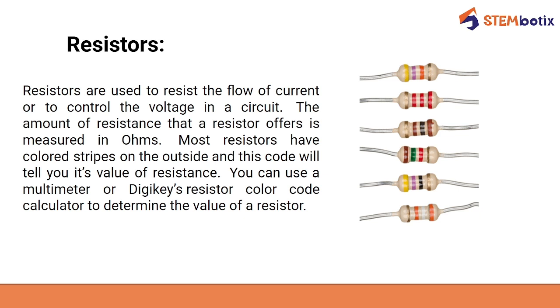You can use a multimeter or DigiKey's resistor color code calculator to determine the value of a resistor. We have seen the digital multimeter, right, just previously. So using that digital multimeter, you can measure the value or the resistance of an unknown resistor.